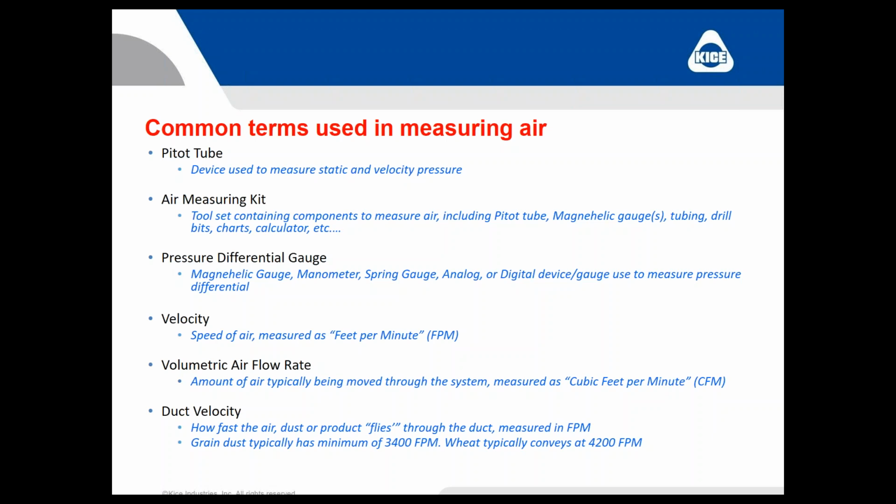Air measuring kit, we throw that around. Basically, it's a kit we can supply, others can supply, that contains the components that you need to measure air, including a pitot tube. Probably multiple magnehelic gauges, maybe a tubing, drill, charts, calculator, that kind of thing that'll help you get the job done.